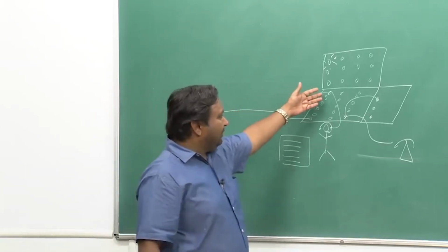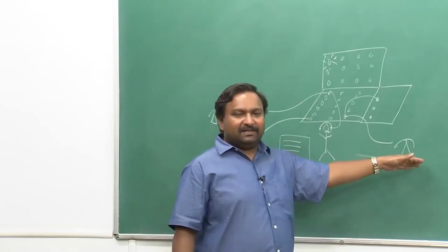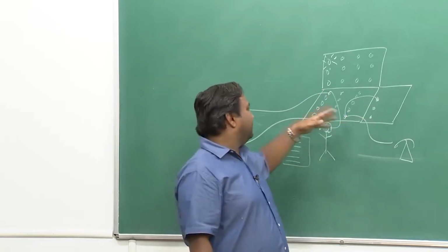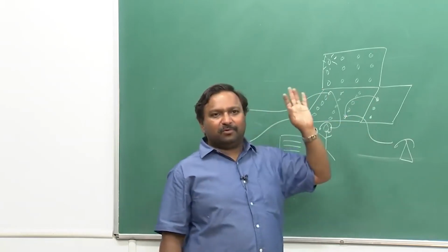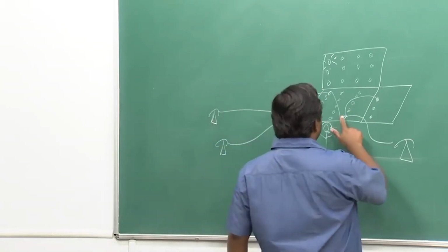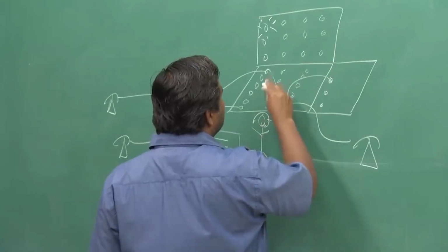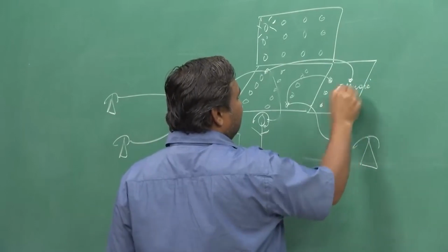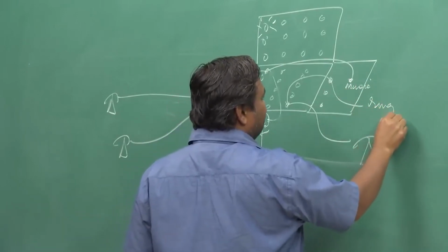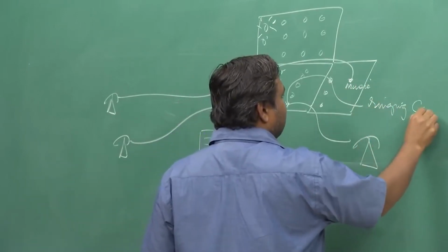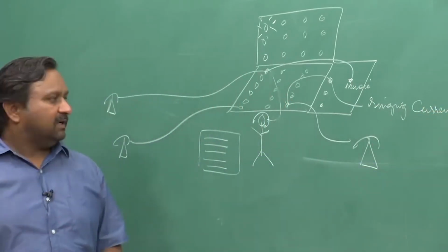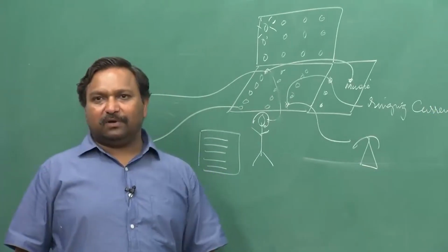Meanwhile, because she is busy making up the connection, this guy can be connected to a music source, so that he knows that his call is going through as of now. So, this is a music source, and this is a ringing current. Ringing current is a power signal which can drive the bell on the other side of the phone.